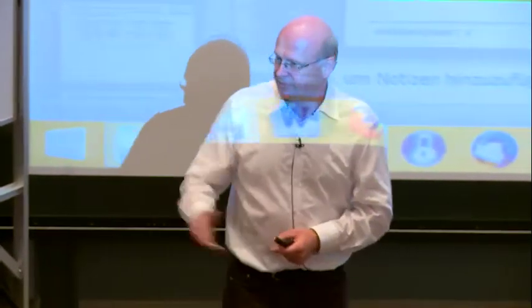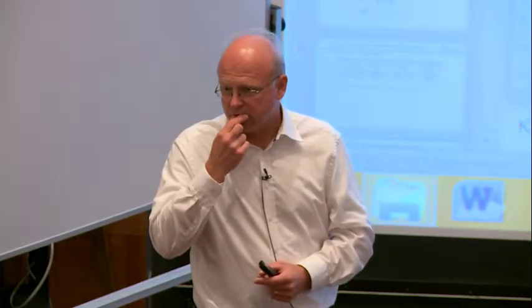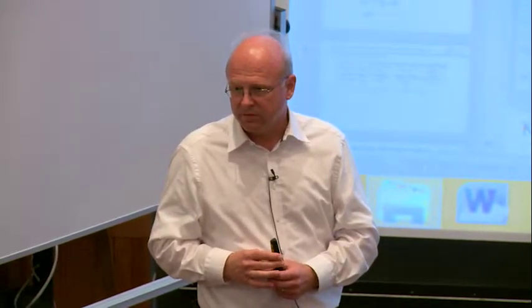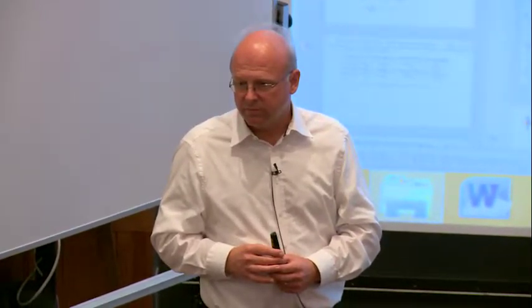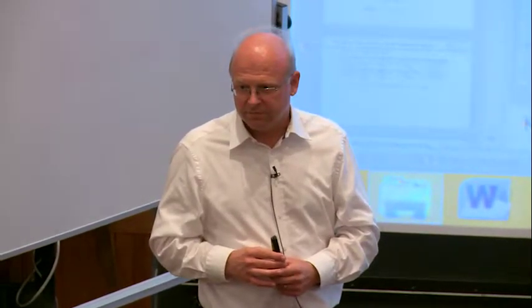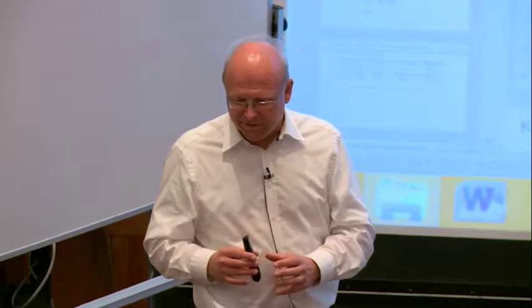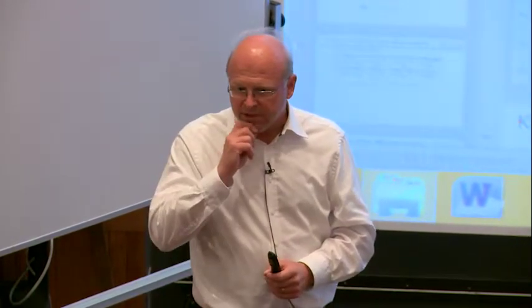You can't resolve it. I've read a couple of papers that claim that the smallest flame structure is on the order of maybe 10 times the Kolmogorov length, and that eddies on the size of the Kolmogorov length scale are not strong enough to perturb a flame structure. So for a measurement like PLIF, do you want to resolve all the way down to Kolmogorov, or can you fully resolve it at a smaller resolution? Go for high resolution only if you're forced to. Okay. Yeah, it depends on the question. I doubt that you can easily resolve the flame structure with OH PLIF, for example.